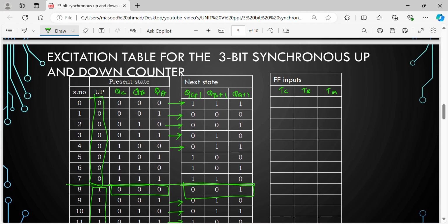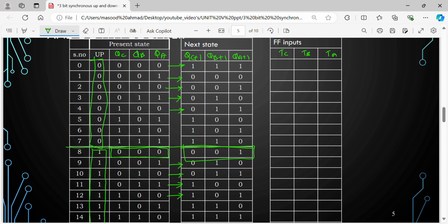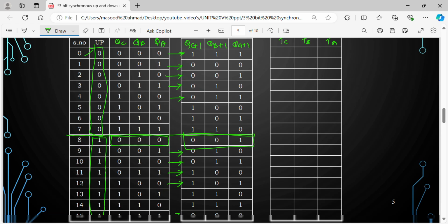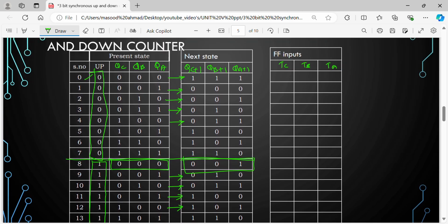So when you consider up as an input signal, the serial numbers, in order to get the minterms, go from 0 because there are 4 inputs now, along with the present state and the present input, which we call PI. The present input of course is up.